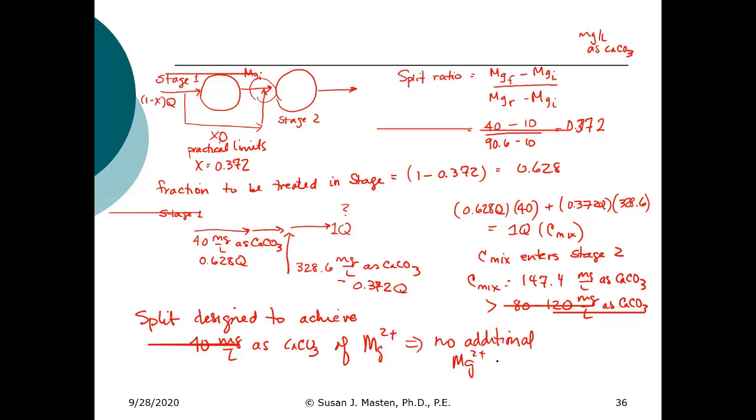magnesium removal. And remember, if we look back at the equations, removing magnesium is more costly than removing calcium, so we will tend to focus on removing calcium if we can and leaving magnesium. What we want to do is remove the carbonate hardness due to calcium versus the non-carbonate hardness due to calcium. Soda ash is more expensive than lime, so if we can avoid adding additional soda ash, we'll attempt to do that.